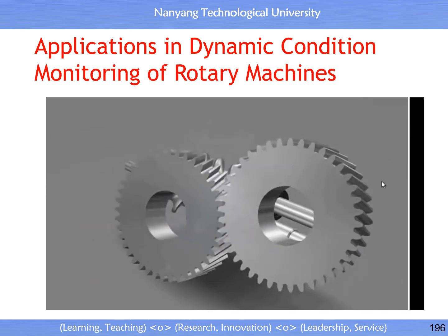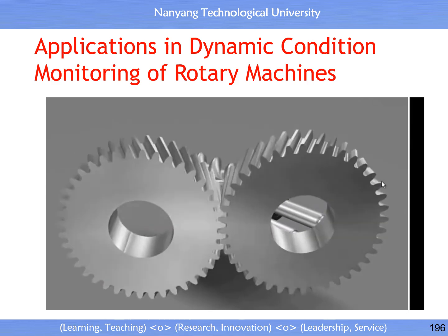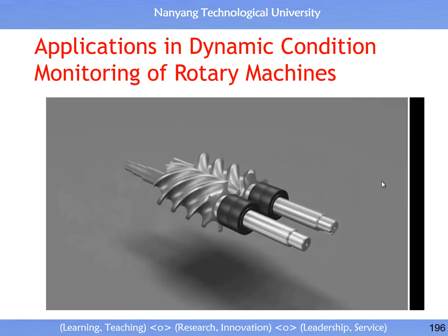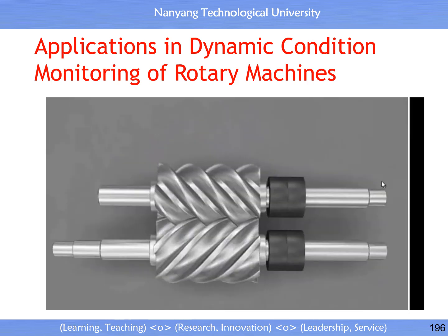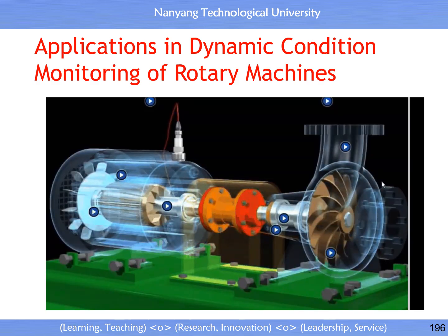Same goes with gears, whether they're timing gears or inside a gearbox. Are they aligned? Are they lubricated? Is there damage to the teeth? Anywhere, whatever the case may be. Vibration analysis lets us look inside the machine.